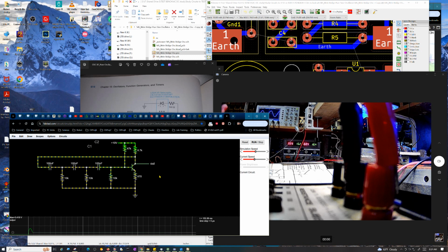Then switch it over to a square wave generator and vary it based on this decade box, or a potentiometer you stick in there instead of the light bulb. So it makes it a versatile oscillator. And again, you can't really do that with a 555, is what I was alluding to, because it generates a DC square wave, not an AC square wave. Now, there's certainly some ringing in it, like you saw.